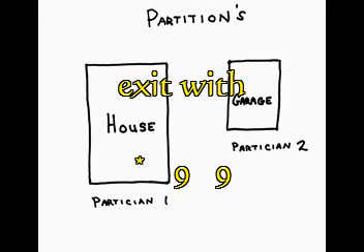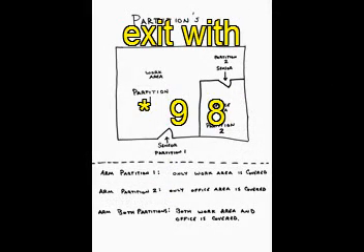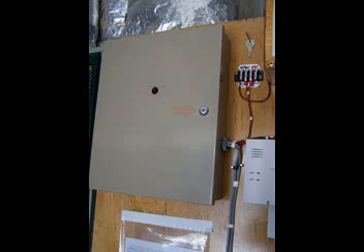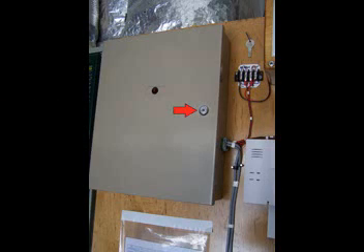A quick recap on exit programming modes. Installing the alarm in your own home, where only people you trust have access to the control panel, exit with asterisk 99. Installing the alarm in a work area, or where strangers have access to the control panel, then put a lock on your alarm box to prevent access to the battery, and exit using asterisk 98. Now only the person that has the key can reprogram the panel.